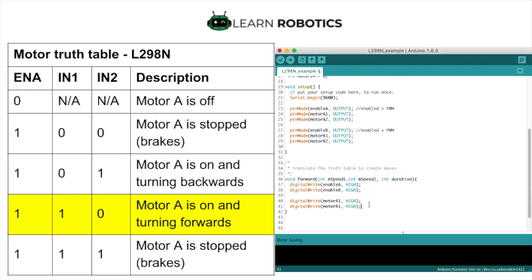What I recommend doing is testing this out and checking that the direction is in fact the direction you want your motor to be running in. If you put this robot on the ground when we download the code and it starts spinning, then you'll know one of your directions is off. It's pretty easy to just change the software to the opposite direction, but you could also change the wiring and just flip the wire leads on the controller.